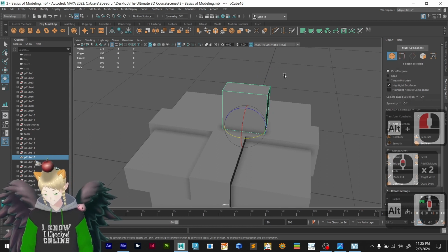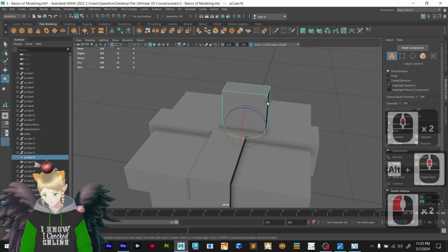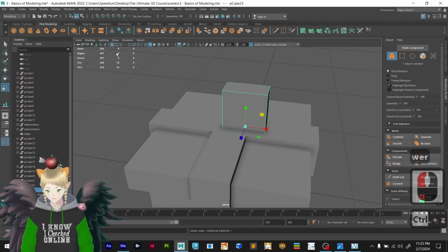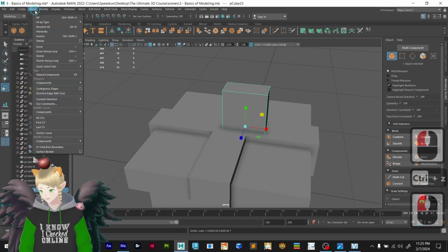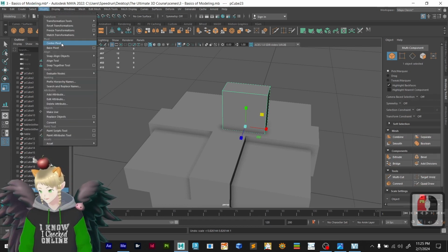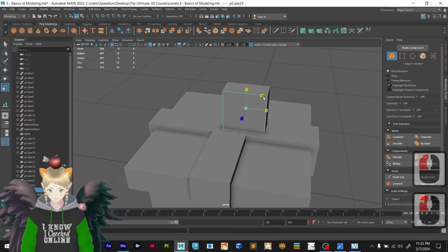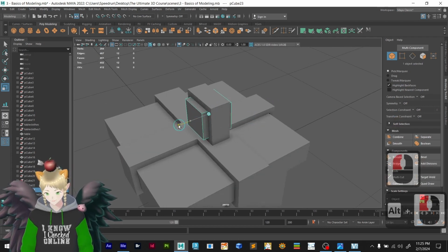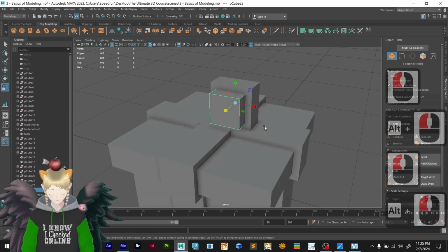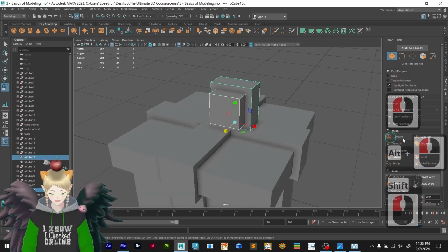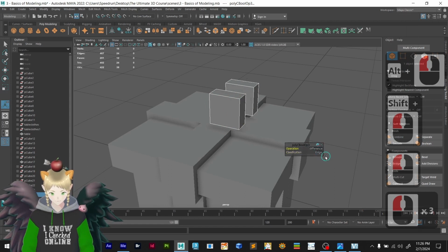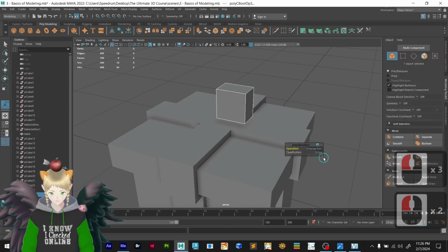Right now I'm going to duplicate this cube, lower a bit. Okay, we need center pivot right now. Select, modify, center pivot. Let's make it a little smaller here and increase the size and use our friend Boolean. This time we want to make difference, intersect.